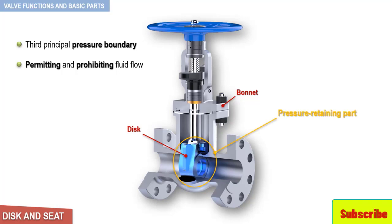Discs are typically forged, and in some designs, they are hard-surfaced to provide good wear characteristics. A fine surface finish of the seating area of a disc is necessary for good sealing when the valve is closed. Most valves are named in part according to the design of their discs. This will be covered in detail further ahead.